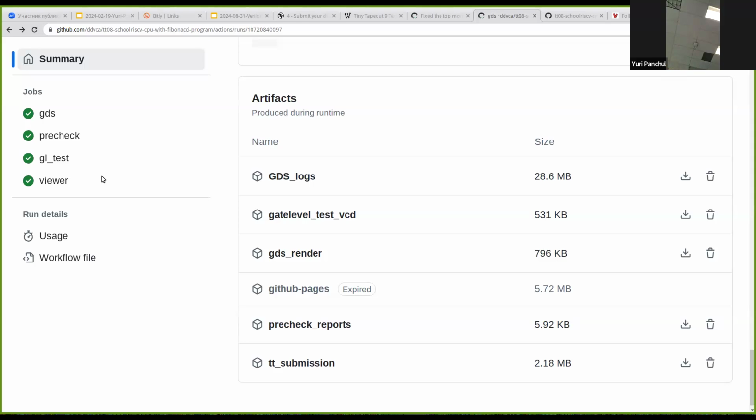So the combinational parts of the design, all the delays, like ANDs, ORs, and so on, the whole path. It can show the maximum clock speed this design can do, or it can show negative slack. I just want to see the report first. Okay, OpenROAD STA. Okay, DRC, manufacturability. Okay, OpenLane generated.